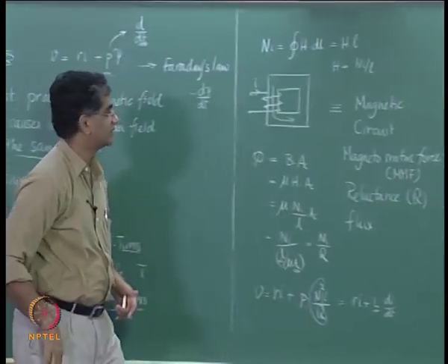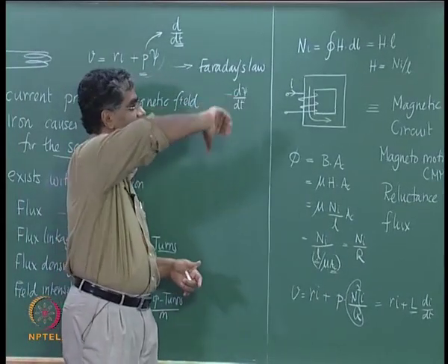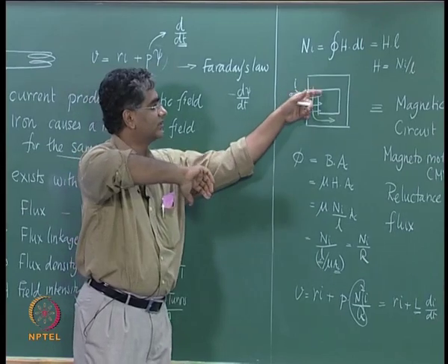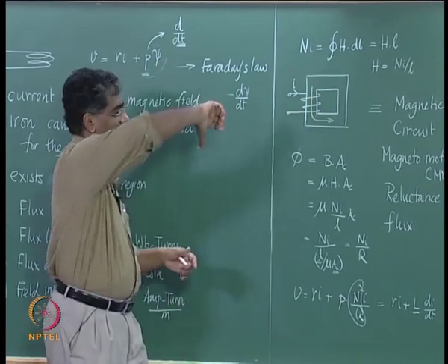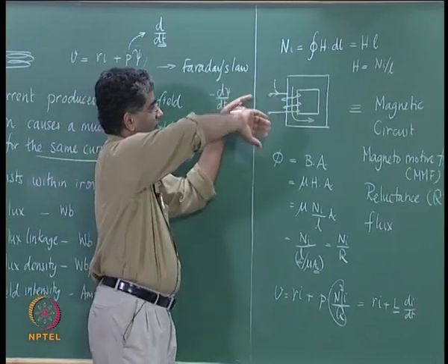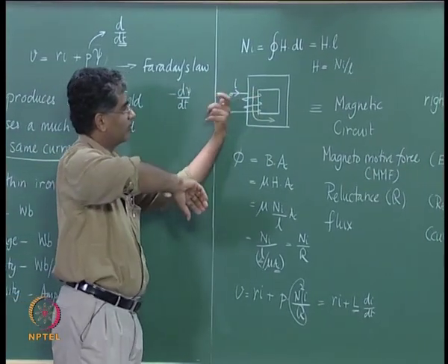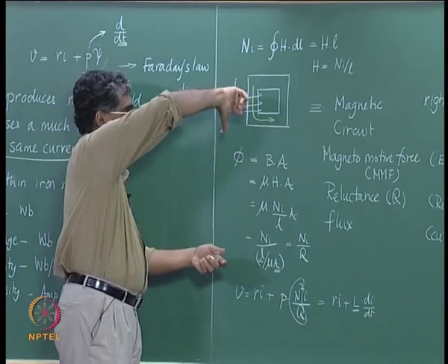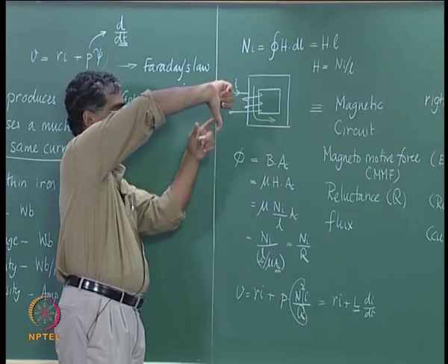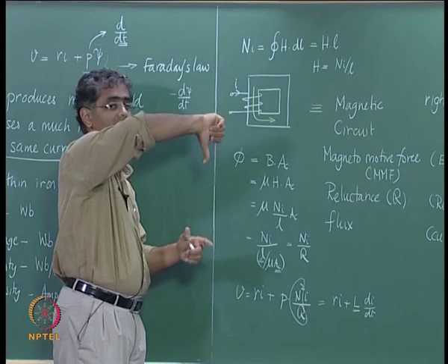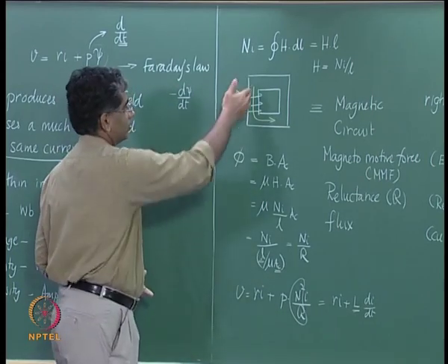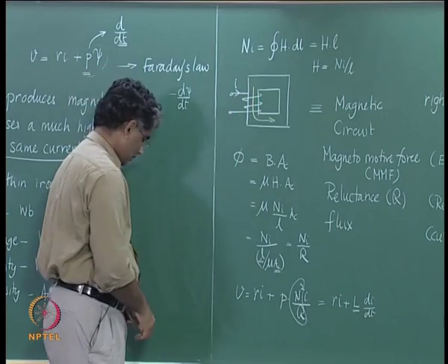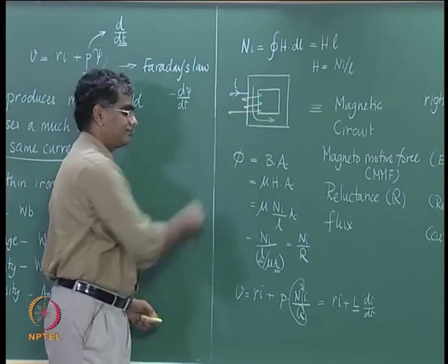which then says that you curve your fingers in the direction in which this current flows around this iron core, which would be like this, because current flows behind the core, comes forward, then goes behind. So it curves around the core like this. Then this finger shows you the direction of flux in the core. So the flux in the core is as shown, that is this way.